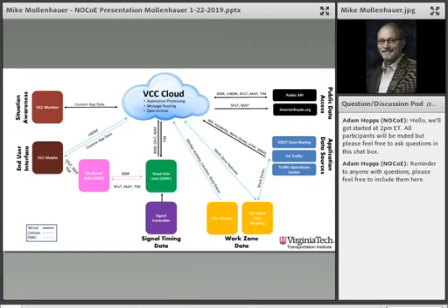Okay, so behind all that equipment that's been deployed on the road, all those DSRC radios, we also have what we call the VCC Cloud. This is a homegrown server-based application that functions as an application processing space. It's a data hub, so all the messages from the system, including BSMs coming in from all of those deployed RSUs, and from a public cellular API also come into the cloud. So they all get brought into the same common spot, and they get archived, or they can also be processed in real time if there are applications that require BSMs from multiple locations.